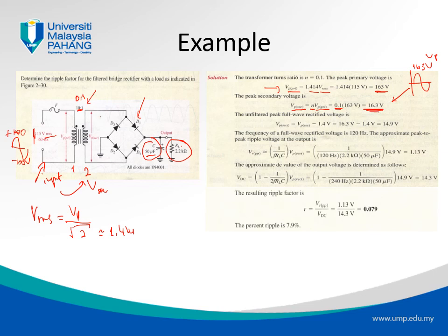Now we have arrived here. The next stage is to go across the rectifier bridge. To find the voltage after the rectifier, if you want to be accurate, you need to take into account the bias voltage of the diode.